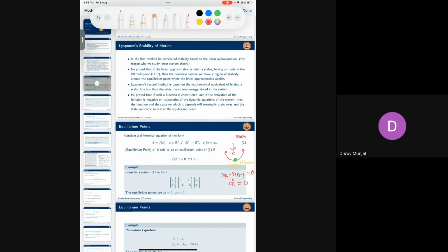So you have to look for the equilibrium point for every system, and you can linearize the system around this point. Whenever I want to design a controller, I am more interested in this area than any other point, because here I don't have to give any extra energy to make the system work the way I want.